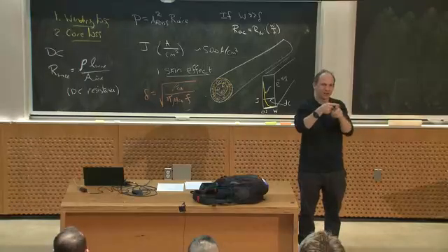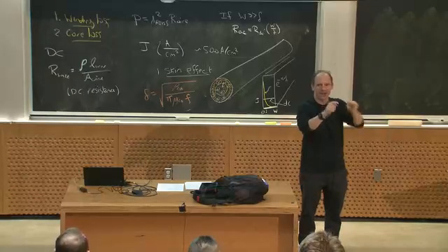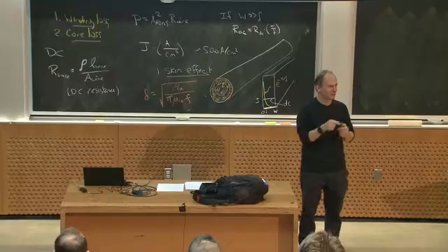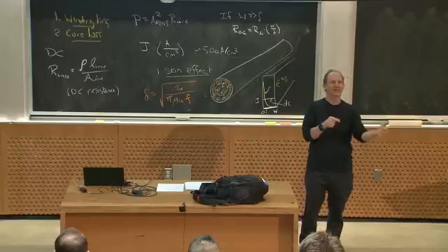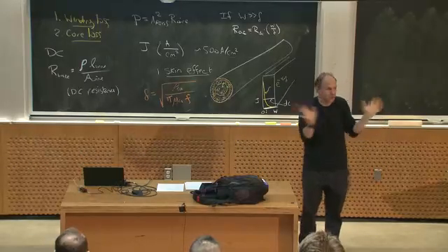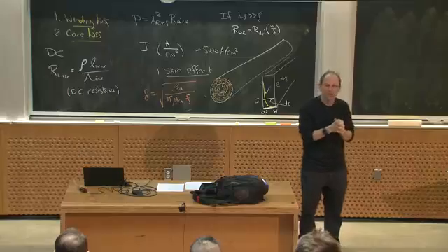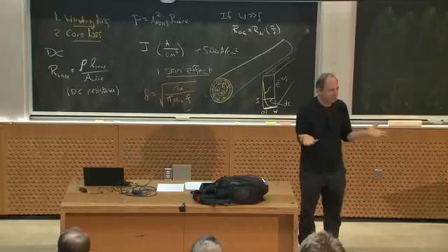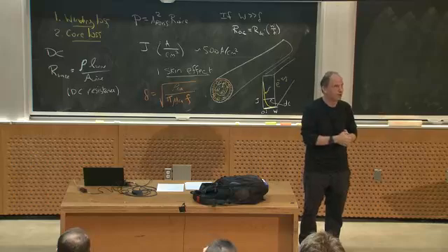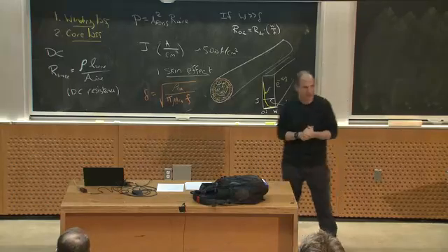So if you imagine that you weave your windings in a pattern called Litz transposition, such that each piece of conductor spends an equal amount of time on the surface and in the middle and the center, then if you want to think about it, the current doesn't know which way to go. They all look equal, so it goes through everybody equally and everybody's happy. So you'll see a lot of high frequency designs where you're carrying high currents that will use Litz wire as the conductor for precisely that purpose.